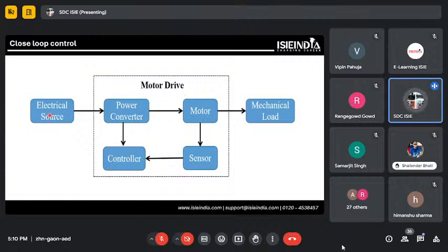When we give electric power supply from the battery, it goes to the power converters inside the controllers, like MOSFETs, IGBTs, and transistors, and these distribute the power supply to the motor. The controller also has an input power supply for the accelerator and its peripheral functions. Microcontrollers are also there, where the predefined algorithms are stored, and as per their responses, they give gate signals and pulse signals to the power converters, and according to that, the power converter distributes the power supply.